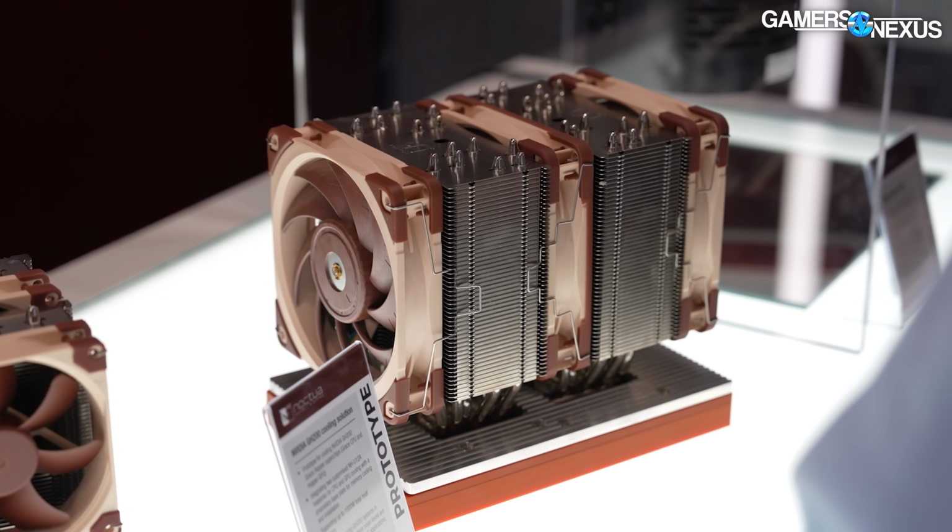So then for optimizing for it, I mean, what are the different types of things you look for when you strap a fan to the front of a heatsink? You're going to have resistance from the fins, so you have to push through that. You have to make trade-offs, I'm sure, on we could pack more fins in here and it would be a lot more surface area. 100%, yes. Right, but then obviously at some point, there's so much resistance, it becomes an issue of can we push through that, and then can we push through it without making it obnoxious from a noise level. So what are the optimizations, big picture stuff that you're doing for fin stacks?